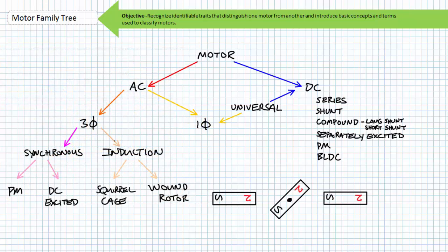Keeping it very basic, if we were to create a stationary field winding consisting of two fixed magnets in close proximity to a third rotating magnet, the magnetic fields would interact such that the norths are attracted to souths and vice versa. Once the armature achieved this alignment, the magnet would just sit there and do nothing. Not exactly the best motor if all you can get out of it at maximum is a single 90-degree turn.